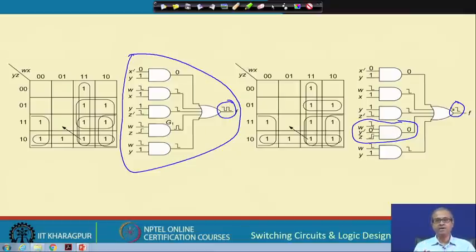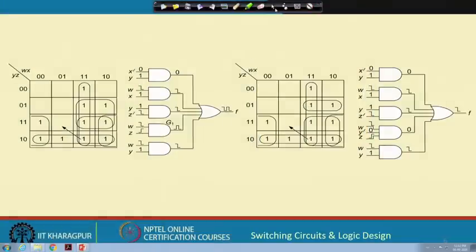Well, I am not going into too much detail of this, just trying to give you a basic idea that this is how it is done. But one thing I think you are appreciating now, that design of asynchronous circuits, making them hazard free, is much more complicated. You will have to look at all possible scenarios for hazards, and then you will have to add additional gates. You see, I am looking at Karnaugh maps here, but think of larger functions, how to handle larger functions, very difficult, right. So, that is the trouble here.